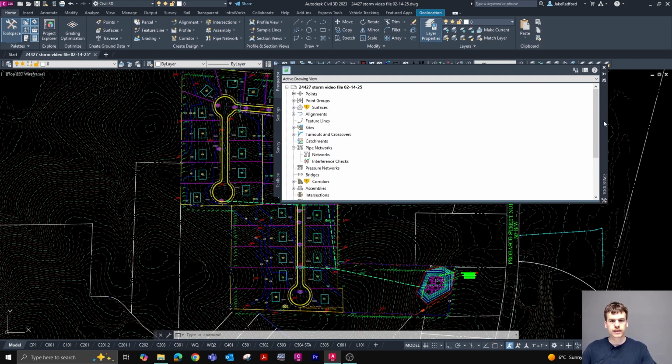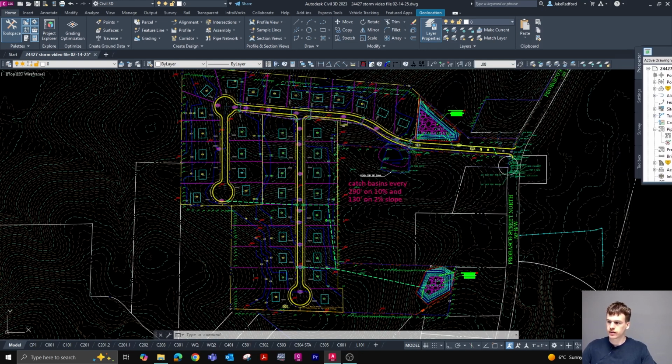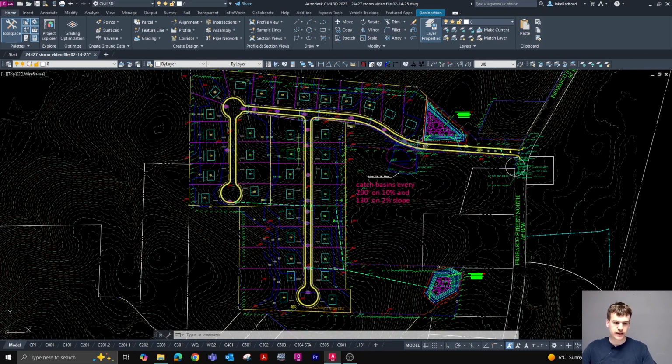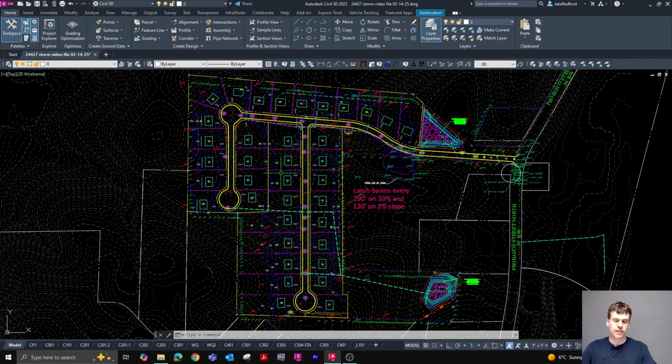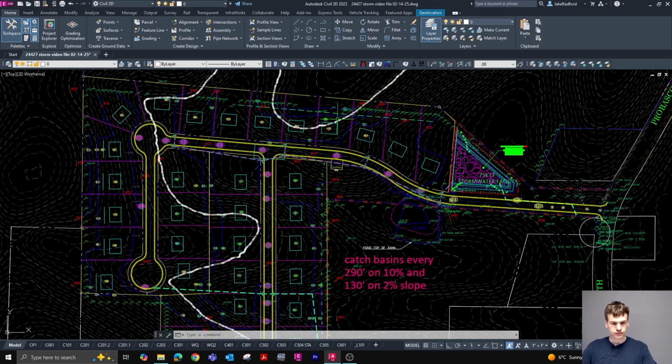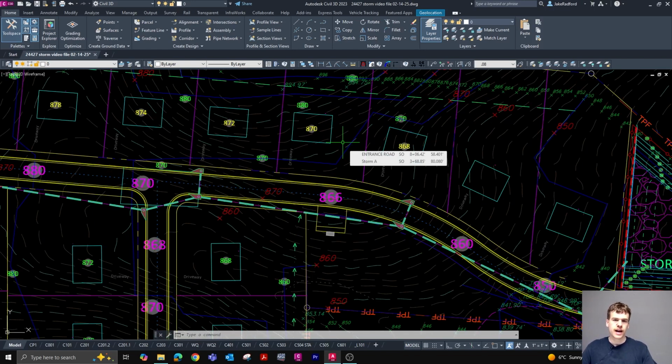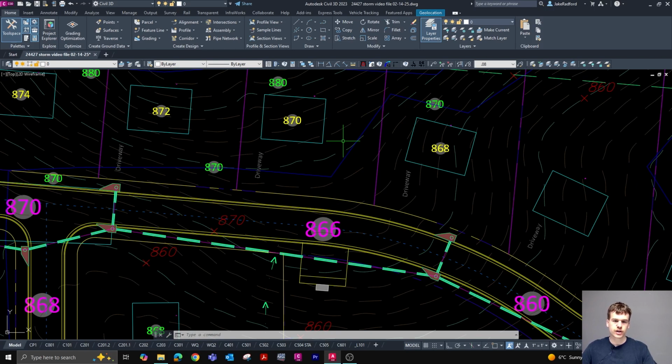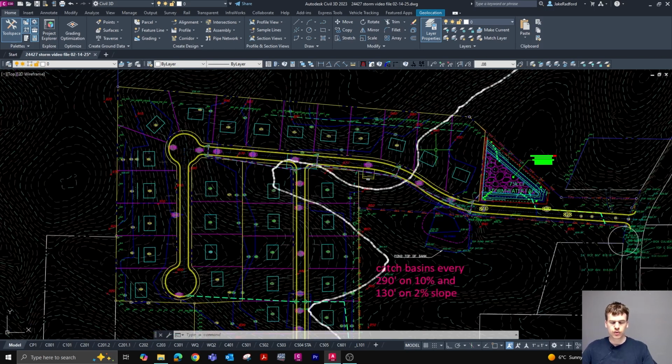Now, again, that's going to limit me when it comes to joining different structures and pipes together, and I'll have to either merge the networks together or create new structures and pipes in order for it to function correctly, which can cause some confusion for inexperienced Civil 3D users. However, I find it to be a better way to organize my files, so that's the way that we're going to do it in this video. But again, it leaves you with multiple choices as the drafter or as the design engineer to organize your file or set up your pipe networks, whatever way works best for you.